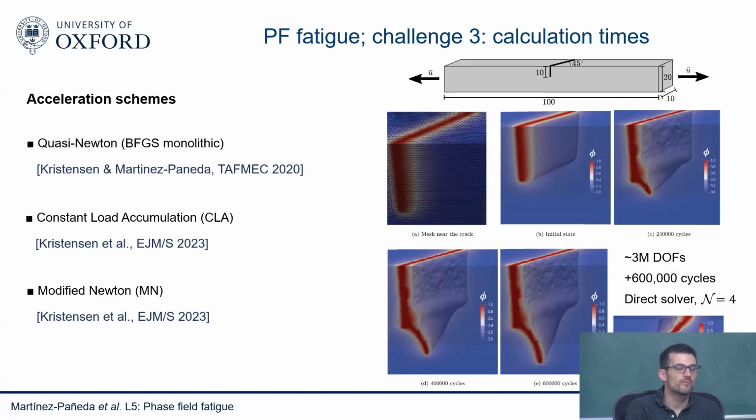This is a question regarding the degradation function for heat. When we use this, does it mean that we don't have to use the damage functions for the plasticity? Because we are degrading stiffness in the fatigue equations, but before phase field, people would model fatigue using degradation functions for the material properties, right? So do we merge them together, or if you use the degradation in the fatigue, we don't have to worry about Chaboche kind of models?